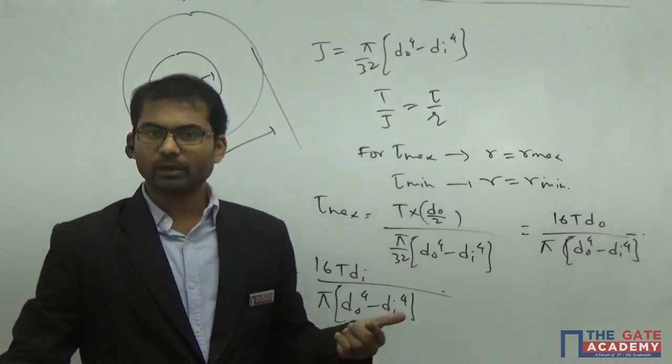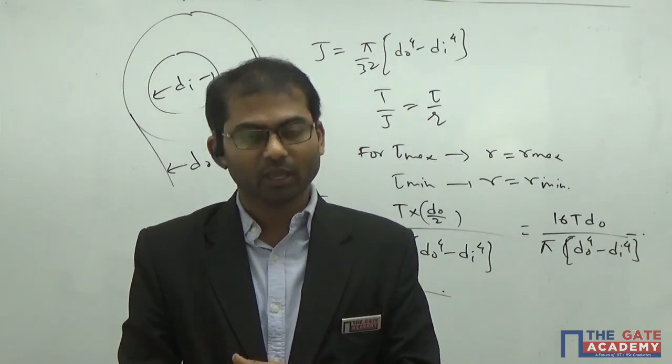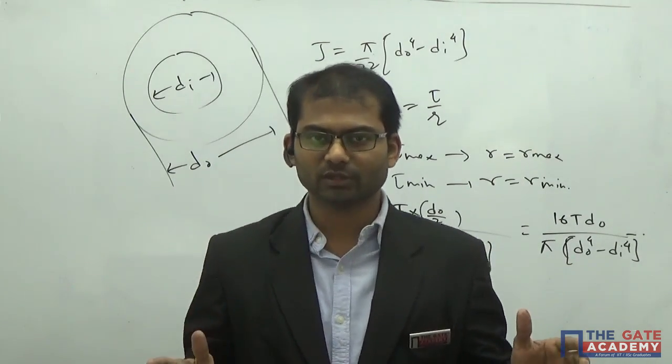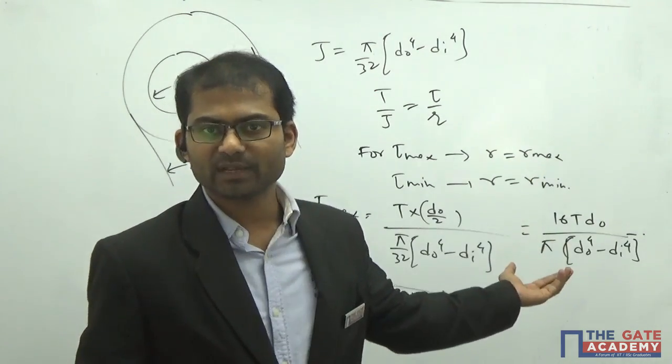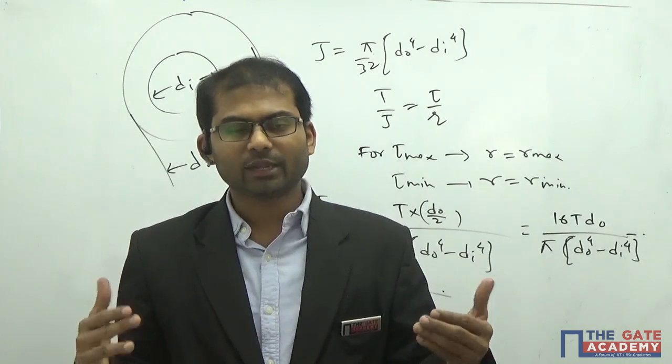I told you that the formula is valid irrespective of the shape and dimensions of the component. Simply, it is experiencing some torsion. That means it must be experiencing some moment about the longitudinal axis. So this formula is valid there. Understand? Your torsion member may even be a rectangular bar also.